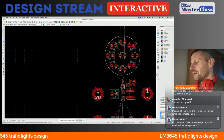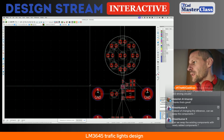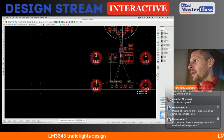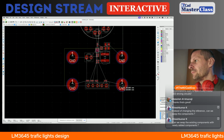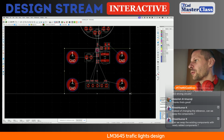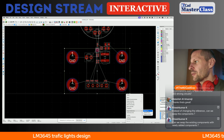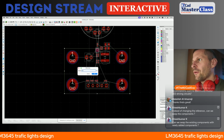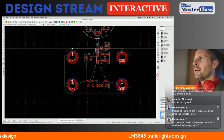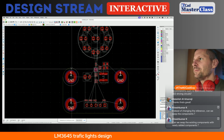0.5 is the verified distance from the center of the mounting hole. Now I am using a trick of creating a rectangle, then shape modification fillet 4.5. Now I can remove this.